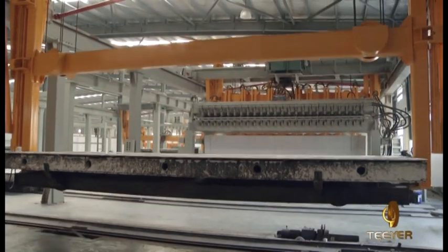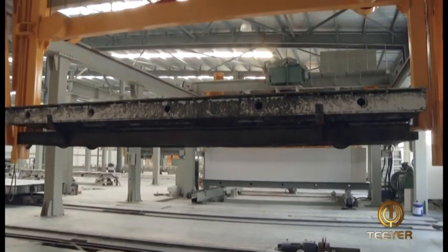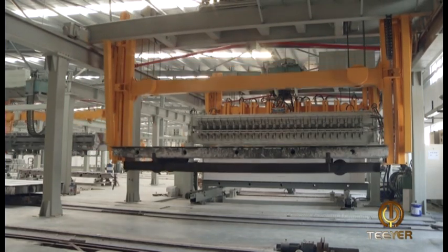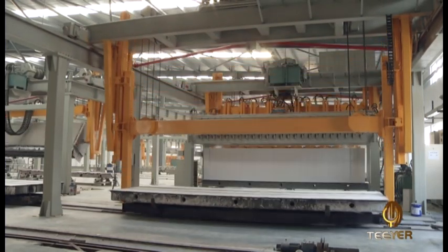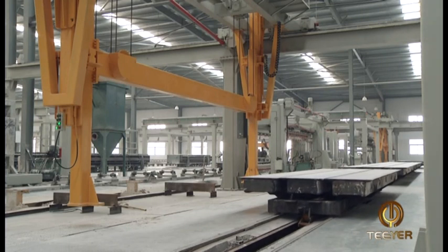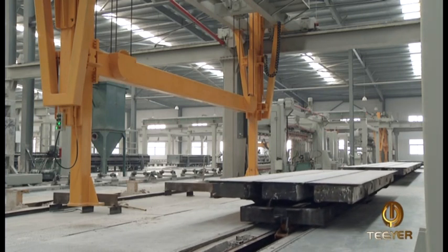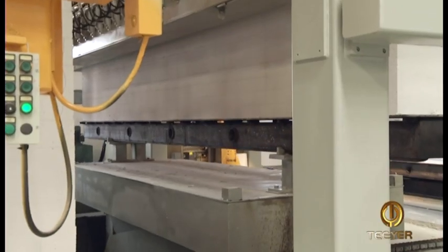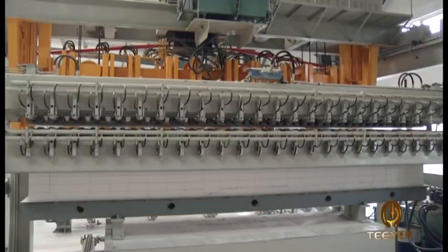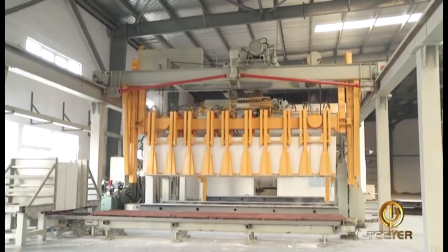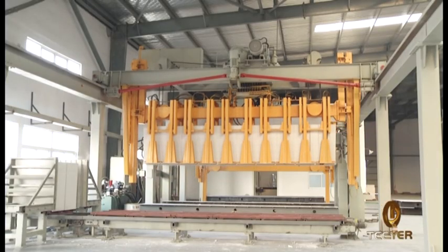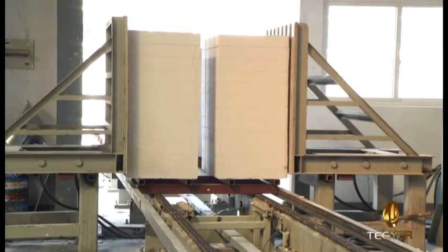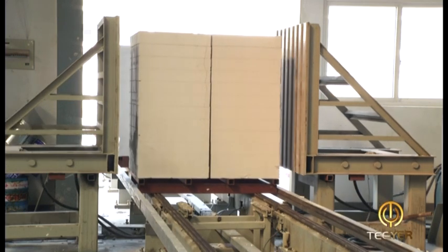After the finished products on the trolley are separated, the demolding hoister takes the trolley together with the empty side plate to the returning line, and it is transported by the conveying device to the pre-marshalling position of the trolley. The traverse device under the separator will carry the finished products on the lifting platform of the separator for separating the finished products. The separated finished products are hoisted by the hoister to the packaging line for classifying and packaging.